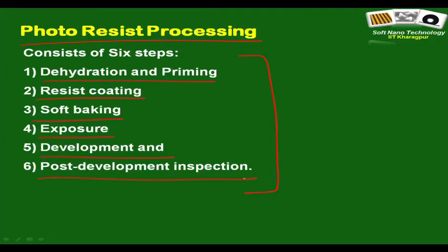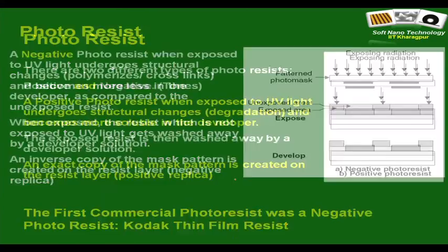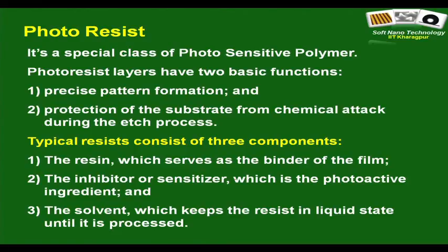So, we understand that you need to have first the barrier coated, the oxide coated silicon wafer comes, and then you need to coat the photoresist. Then the soft baking is a particular step I will mention about it. Then you need to do the exposure, then you need to do the development and so on. There is a bit of discussion in the PPT, since you will be having access to the PPT. So, I will not repeat everything, a bit of discussion on the photoresist,